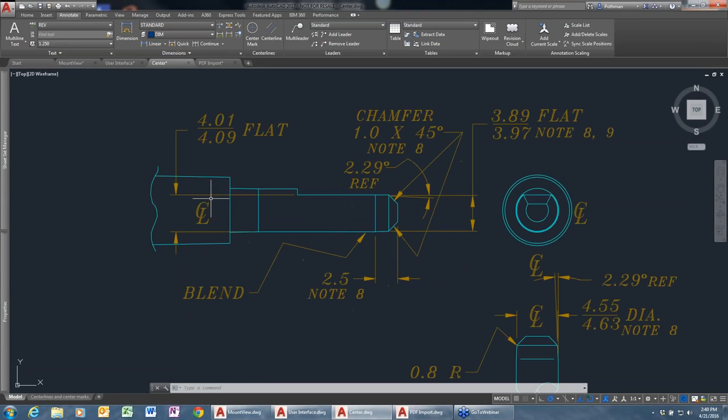You can see that these two lines here are not even parallel, but I want to draw a center line between this part, connecting to the cut through the middle and through the other elevation here. There's a new centerline command. It's on the Annotate tab, and it's called centerline. I just select the objects that I'm interested in adding a centerline to, and it'll go ahead and add in that centerline.